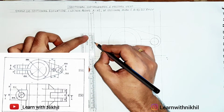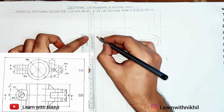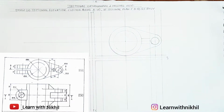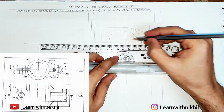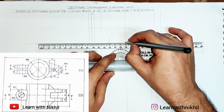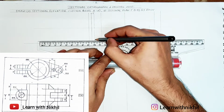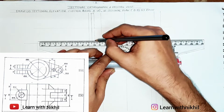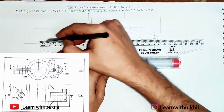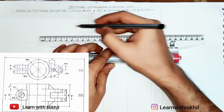Now drawing this part, I'll mark a point 5 millimeters above, then 10 millimeters below, 5 millimeters, and then 10 millimeters. So this is the thickness of the semicircle. I will draw parallel lines through it, touching towards the circle. I'll extend these lines to the right hand side view.